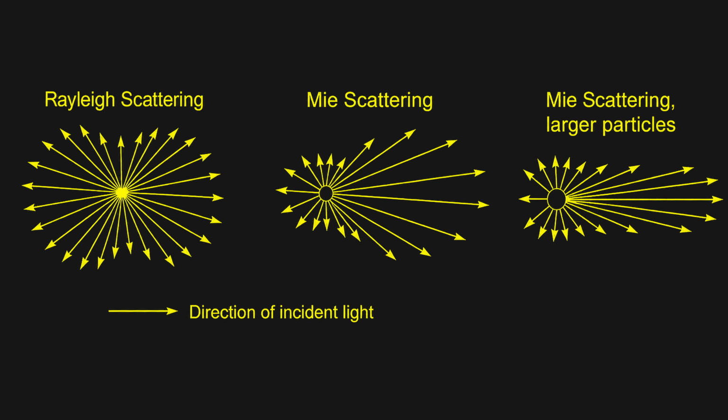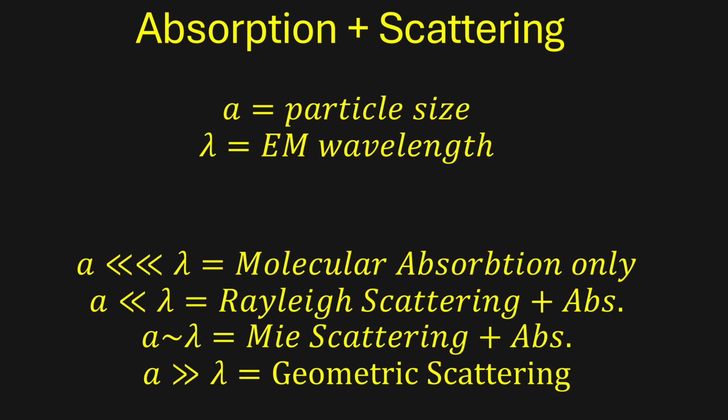When electromagnetic waves pass through much smaller particles, such as molecular water and oxygen, there is minimal scattering. Somewhat larger particles, like liquid water droplets in clouds, will have broader absorption and can create Rayleigh scattering, but at RF frequencies, Rayleigh scattering is somewhat minimal. So the significant term is Mie scattering, which occurs when the particle diameter, in this case millimeter scale rain droplets, are similar in size to the wavelength.